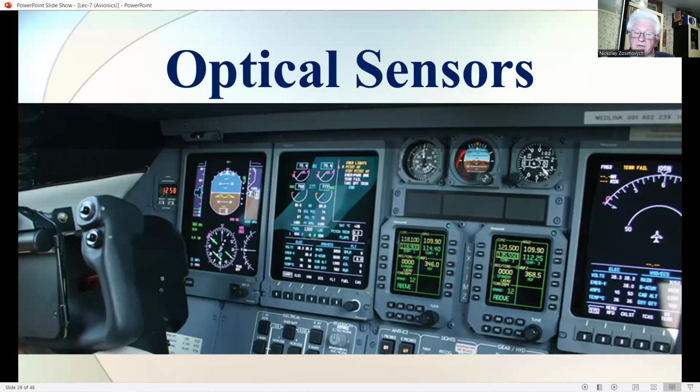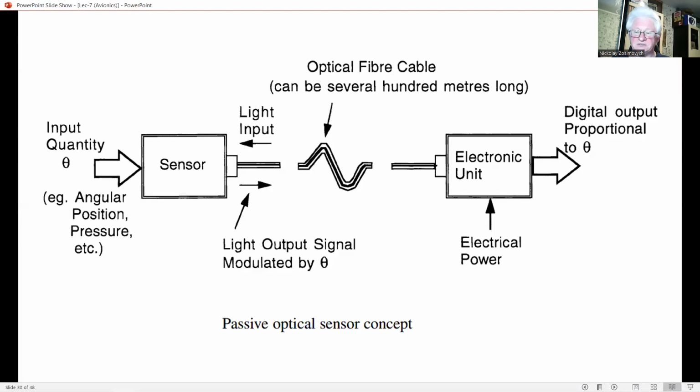The approximate location of sensors is indicated, and it can be seen that many are located near the extremities of the aircraft and possibly less well screened than fuselage-mounted equipment. The extensive use of composites can further degrade electromagnetic screening in the vicinity of such sensors.